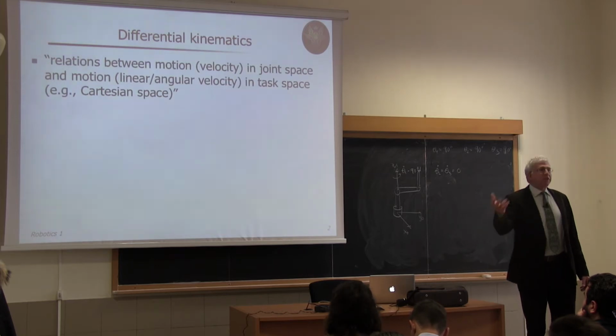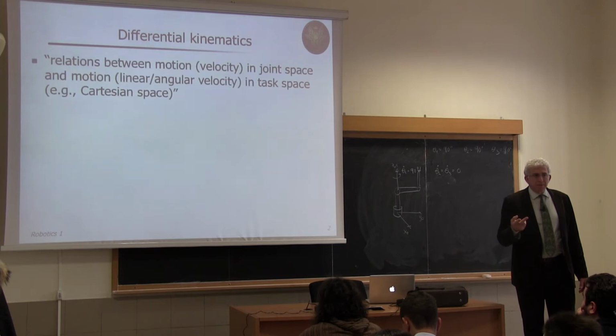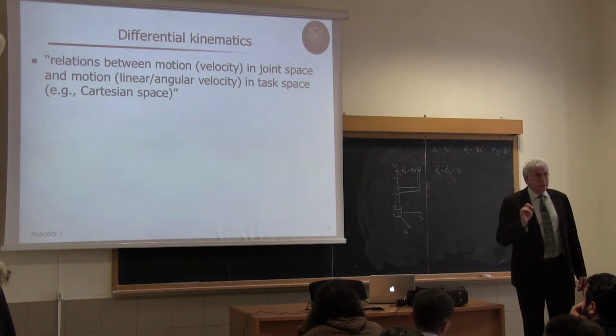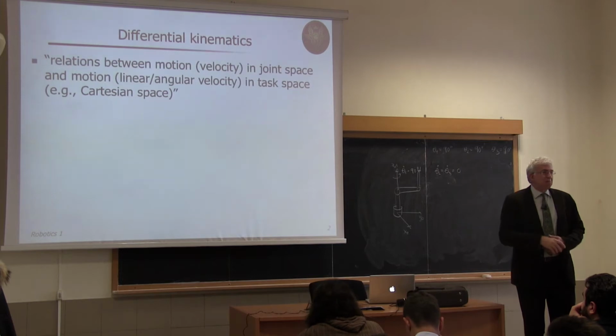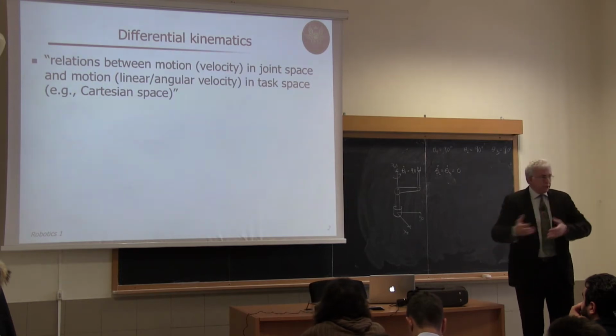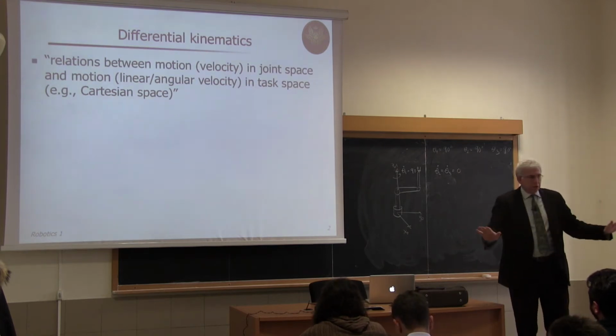So what is the inverse differential kinematic problem? Just reverse things. And exactly like for direct and inverse kinematics, you remember we commented on the fact that direct kinematics is an analysis problem. I give some configuration, I compute position and orientation of the end effector. Full stop.